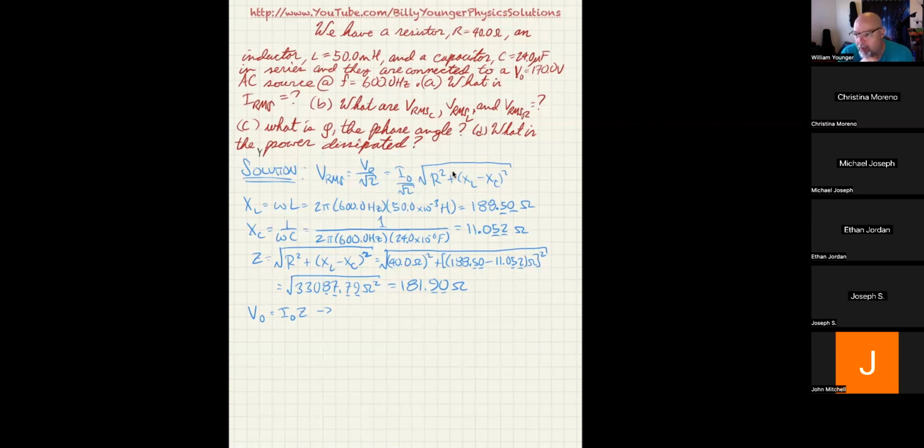But if you were taking this in a more advanced class, what they would call XL they would actually say is omega L. And then what they would call XC would be basically negative one over omega C, but that just adjusts the phase too. So it's useful for that. Now, the net effect is there's a little tendency to pull the voltage ahead of the input voltage.